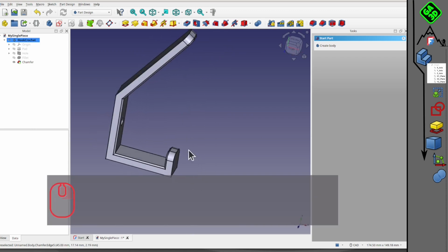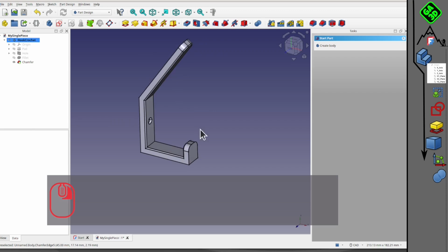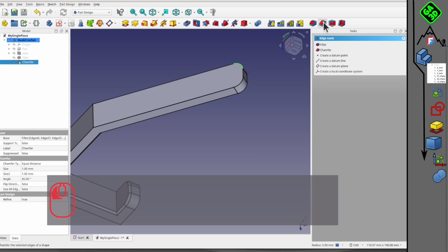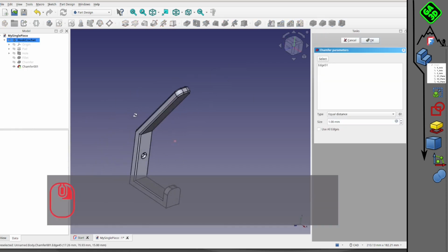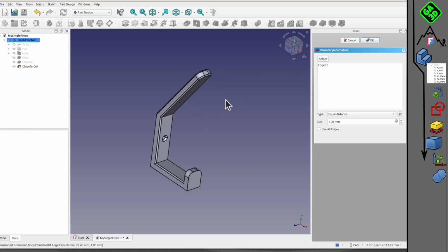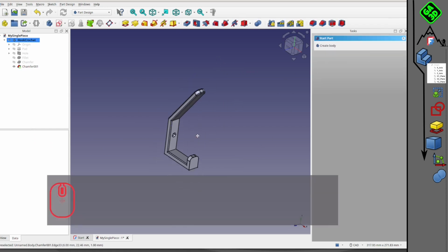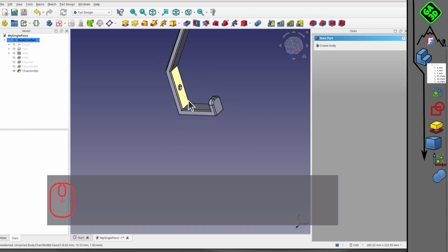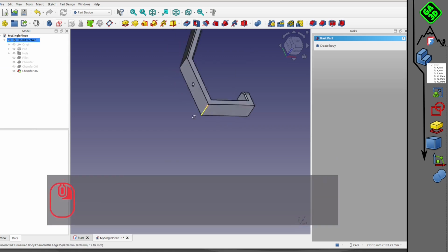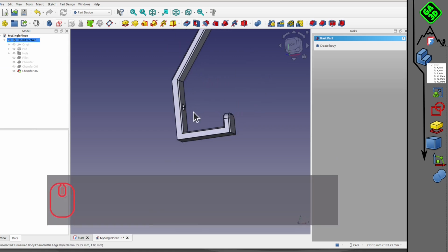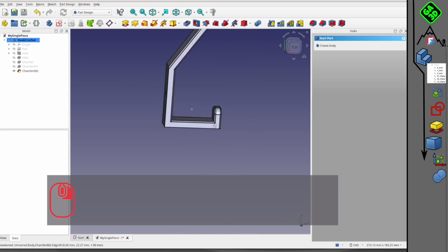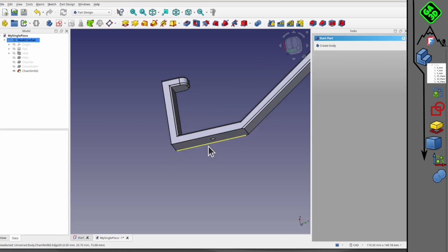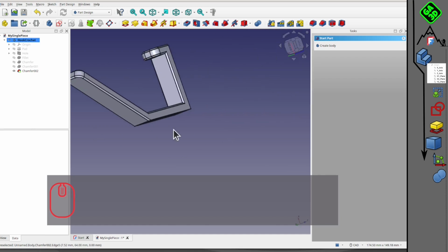So now we're good. I'm going to add some more chamfers here again. It'll make the piece a little softer. And again in front too. There you go. That way, it's not bad. Here, I have a lot of chamfers. Since it's going to be screwed against the wooden board, under there it's not necessary either. That way, when I print it in 3D, I'll get better adhesion, because we won't have chamfers on all sides. So here's my hook, the single piece is finished.